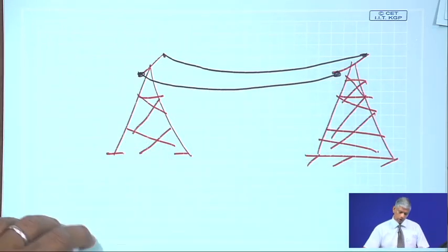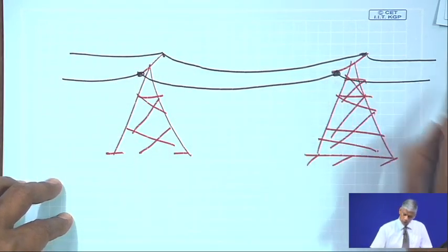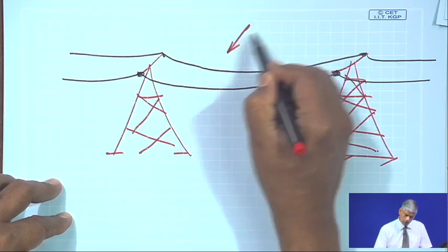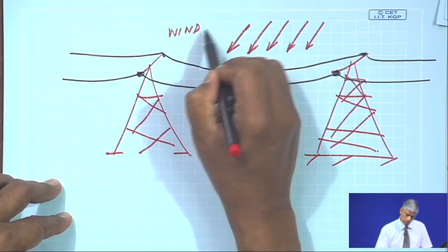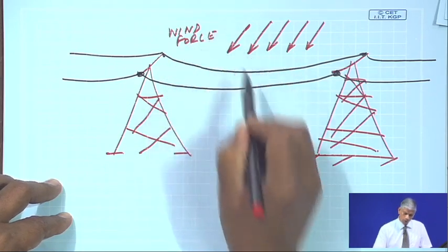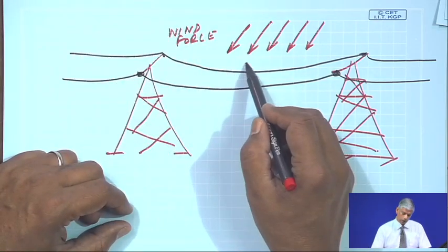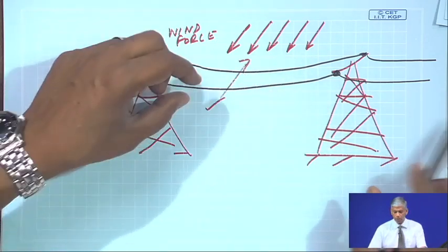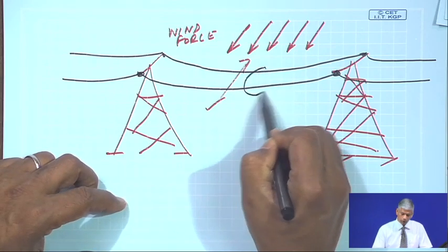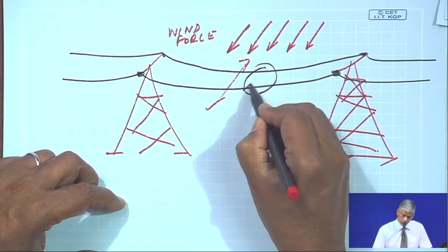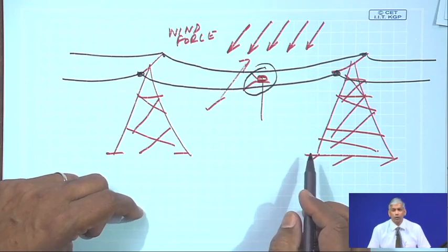Now, imagine this continues to another pole and so on. Imagine if there was a large wind force. So, what would happen? These electrical conductors would sway in the wind, and their amplitudes of oscillation would be so high that one may touch against another. So, some sort of a touching can occur, and then you can see the consequence of a major contact of these two conductors.